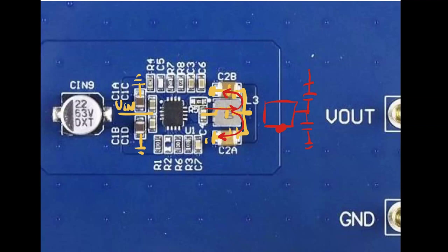As you talked about the coupling between the two magnetic components, is it a big problem when I put the input filter and the output filter close to each other? Yes, yes, it's very, very important. Very, very important. Typically, this is not considered. Many designers that are not familiar with high frequency effects don't believe this coupling until they see how important it is.